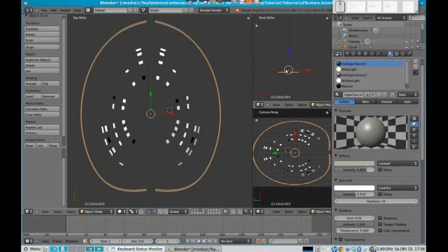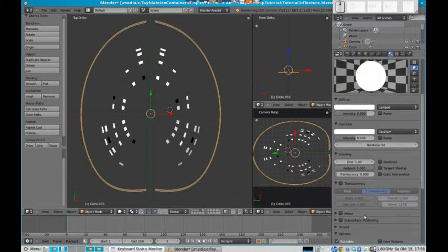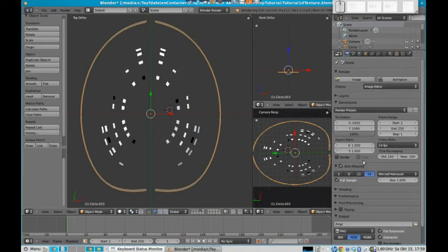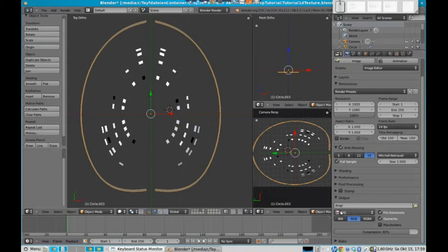No, we don't need the lamp, since the window light has an emitting value and we will see that all the time, even if no lamp is there. And the black parts will be black if no light is coming on them too, so it's okay. But of course the background shouldn't be black now. So let's go to the rendering part and say we want not an RGB PNG but an RGBA PNG. So only the things which are really black are black now, and all of the background will be transparent. So that's actually all. Let's animate that.